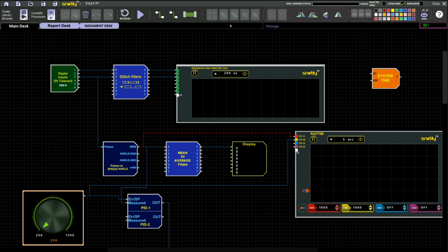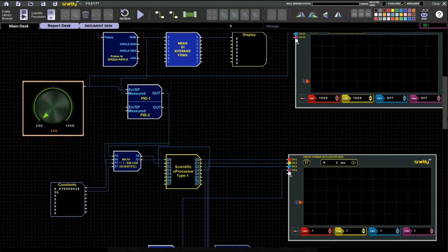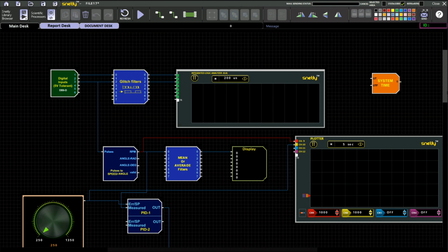This is the model required to run the motor in closed loop speed control action. Only one block we have additionally changed: the PID block. In open loop we are not using the PID block. Here we are going with the control logic of PI for the closed loop action. Similarly, there are different control techniques for running the motor in closed loop.